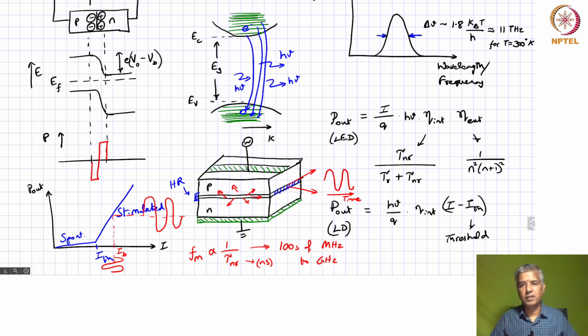So that's one of the advantages of using a semiconductor light source. Your modulation frequencies through this direct modulation process can achieve up to hundreds of megahertz to gigahertz. That is a very big advantage, and later, when we are designing a sensor, we will see how this modulation capability is very beneficial. Okay, so I think that's good for now. We will continue with talking about optical receivers as we move from here.